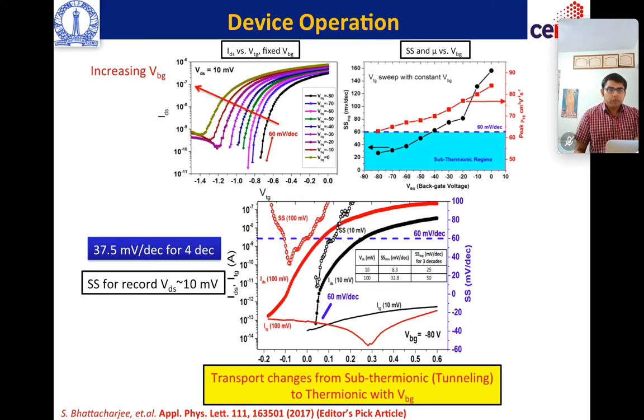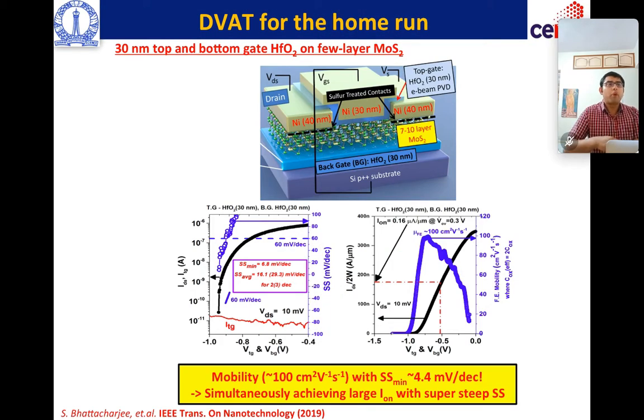Dual-gated MoS2 FETs are fabricated with careful deliberation of device architecture and materials processing. This device is capable of operating in 2 distinct regimes. First, a low-power tunneling regime with steep subthreshold slope and operational voltages of less than 0.5 volt, or a high-mobility, high on-current thermionic regime. Next, an intuitive modification in the device structure can dynamically tune the transmode from off to on state, thus combining the dual benefits of tunneling and thermionic transport in the same operational cycle.